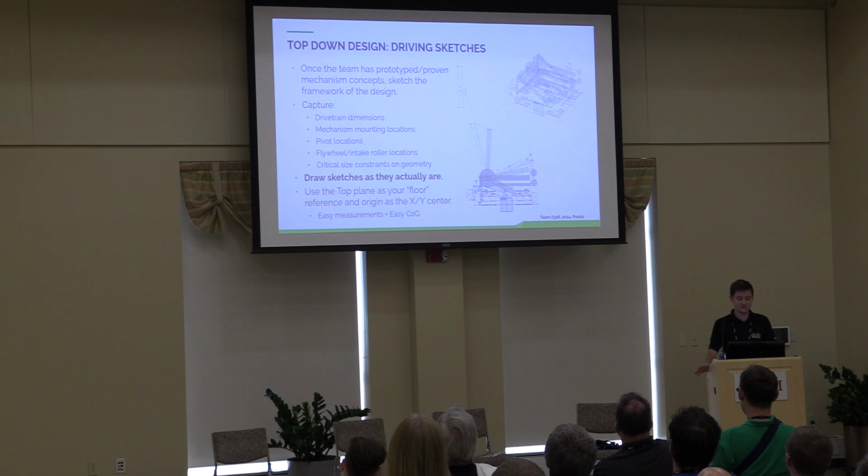Also, I like to say, draw the sketches as they actually are in real life. And what I mean by this is use the top plane, the one that is on the XY axis, use that as your floor.